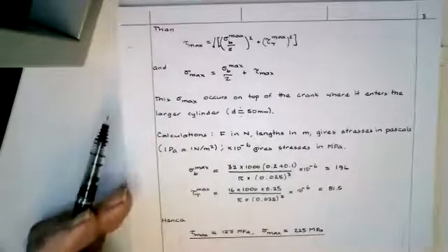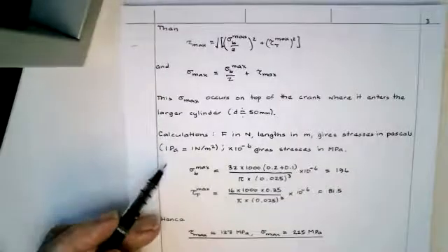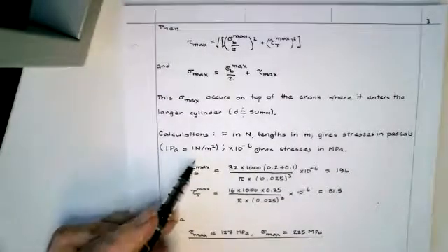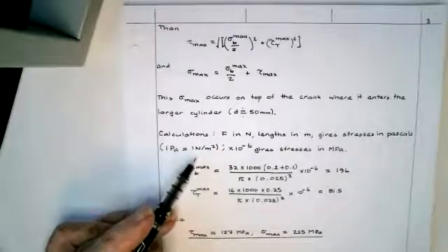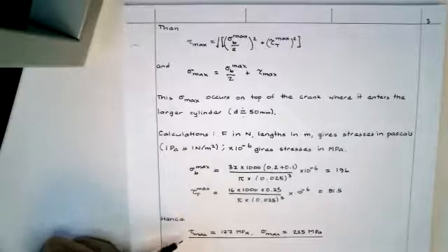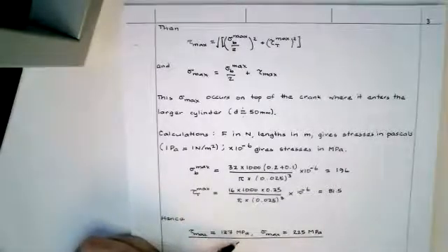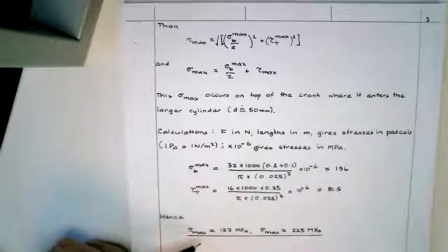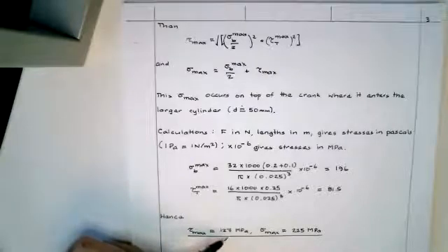When you're working with SI, you have a Newton over a meter squared. That's a Pascal. Newton per meter squared is not really a unit; you should call it a Pascal. More often than not, for the sort of magnitudes you'll be dealing with, you're talking about megapascals, or 10 to the 6 pascals. Strictly speaking, in SI units, you're not supposed to have numbers bigger than 1,000.